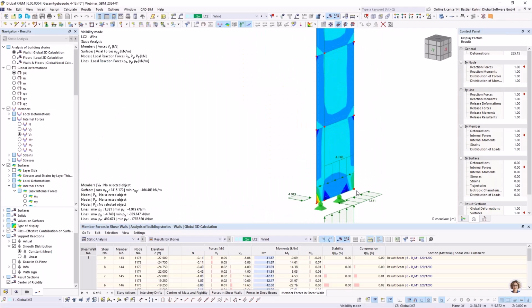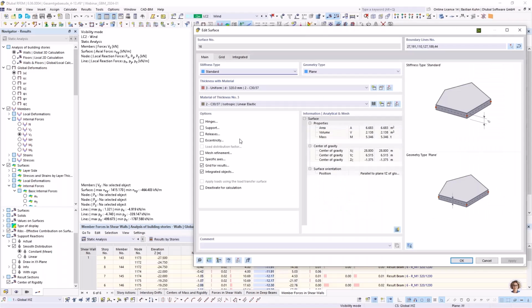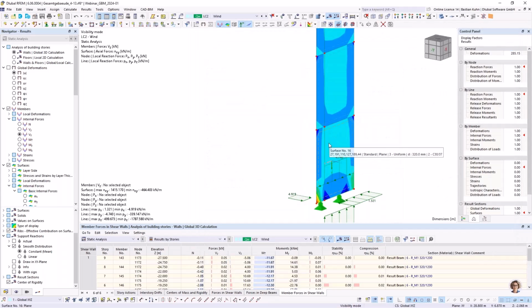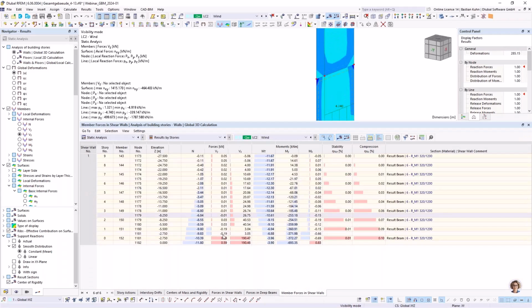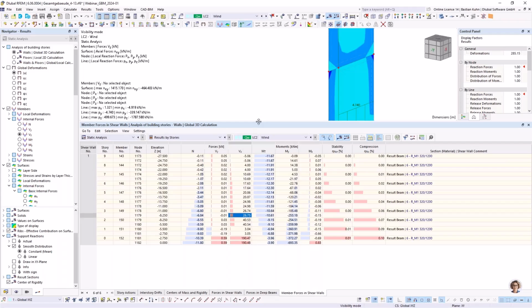You can see, okay, load transferring is, as I already mentioned, done by the surface itself. If you model it to have a reduced stiffness, if this would be a CLT wall, it would include the reduced stiffness. If you have defined a line hinge in here, that would be regarded. But right now I did nothing with it. It's using this shear force in between, and that's the result that I have. Of course, I can always have my shear force integrated here via the result beams. This is also done automatically by this add-on building model. All right.